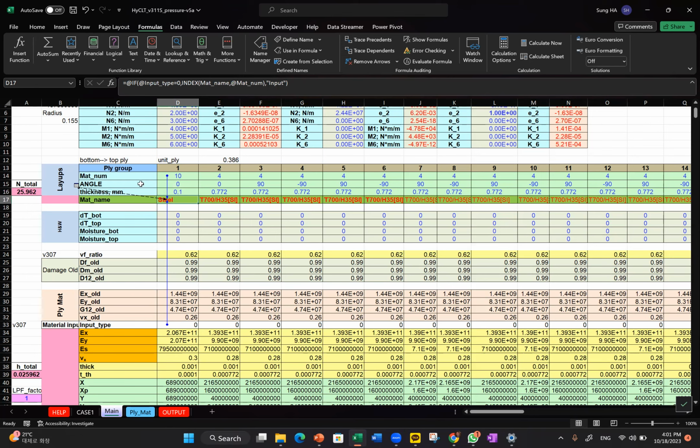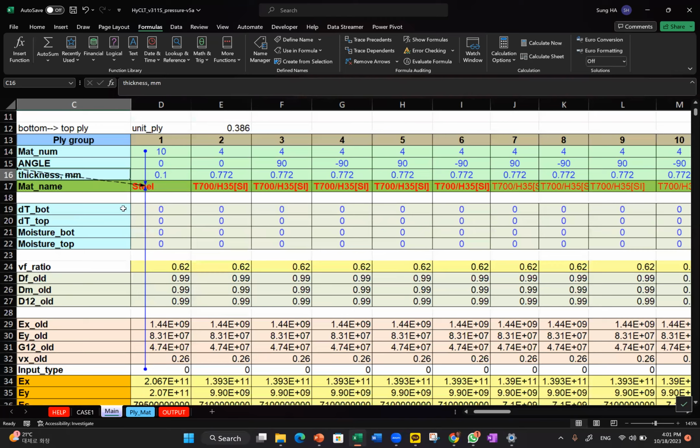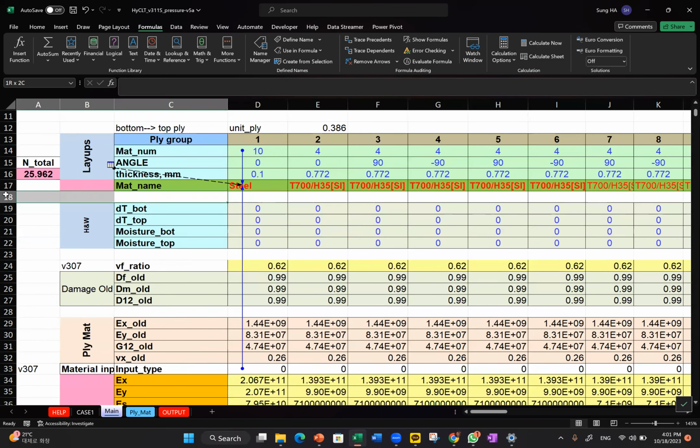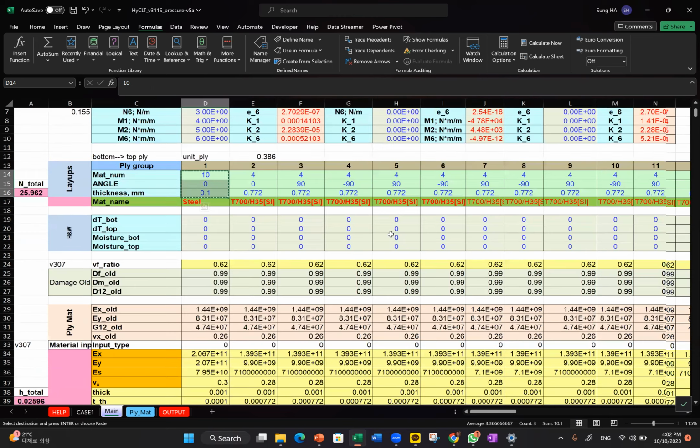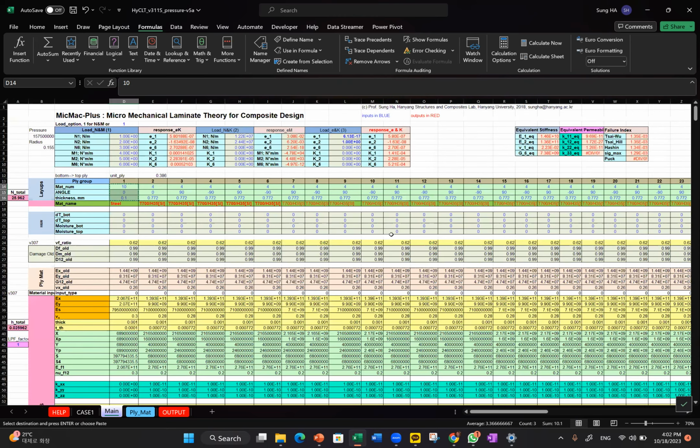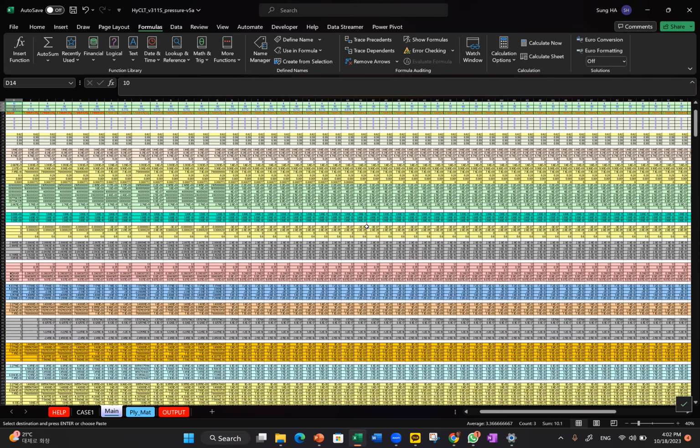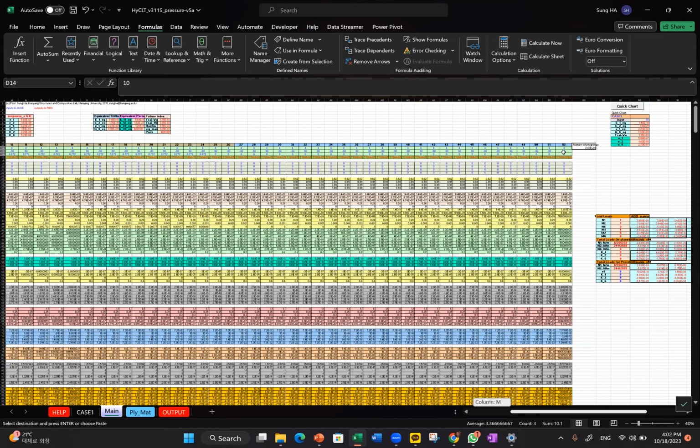Always remember there is a unit there. In this case, we programmed the thickness unit to be millimeters. So, okay, a 0.1 millimeter thick steel plate is stacked there, and then we can have as many as you like. Let's say the whole range up to here.